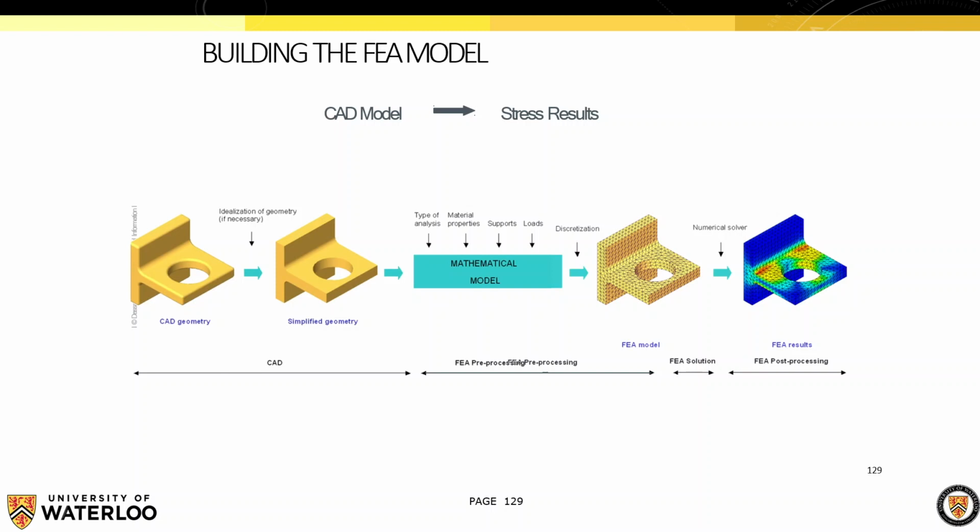You're just doing the force equilibrium on that particular element, and you're propagating the result of that as the input to the next element. Okay, and from there, once the computer solves this entire set of equations simultaneously, that's where you're really leveraging the power of the computer. So they're very simple or repetitive calculations that are just performed many, many times on these elements.